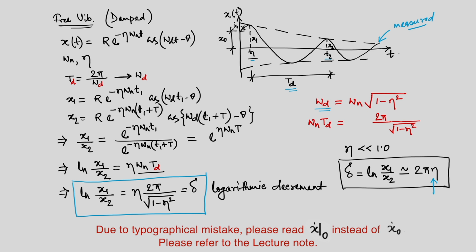The moment we find out the critical damping ratio, then again using the relation of damped natural frequency and natural frequency, we can find out omega n. So, that completes the exercise. So, we can measure the response, and from that we can find out the critical modal parameters of a SDOF system. The two parameters are natural frequency and critical damping ratio.